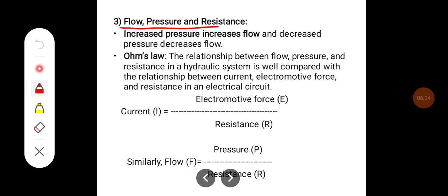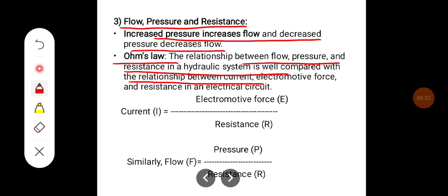Then flow, pressure and resistance relations. Increase in the pressure increases the flow, and decreased pressure decreases the flow. So Ohm's law, the relationship between flow, pressure and resistance in a hydraulic system is well compared with the relationship between current, electromotive force and resistance in an electrical circuit.